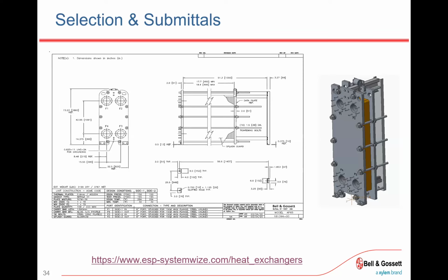If you didn't have flow in the system and your boiler water were circulating, that's going to be satisfied. It's thinking you're achieving it when in reality you're not circulating out to the system. And it could be skewed by the imbalance in flow rates. If you have that downstream on the system side, 10 feet or so, then at least it's likely to only be satisfied if you have flow in that circuit. Of course, yeah.